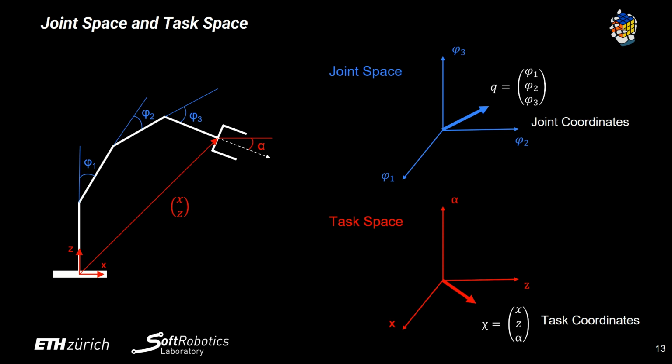So here we show an example in 2D only, to help understand joint space and task space. Please note here that although they are represented in the form of a 3D space, they are essentially different from the Cartesian space that we introduced earlier. You can probably already tell by just looking at the notation of the axes. For a robot with full degree of freedom in a space and no redundancy, the number of coordinates in the joint space and task space should be the same.